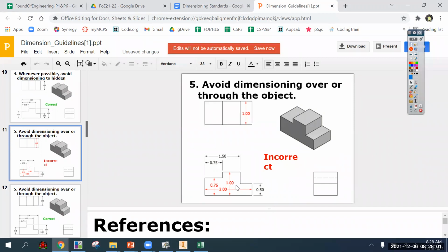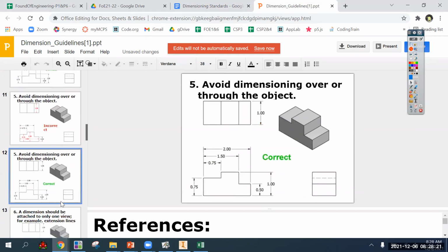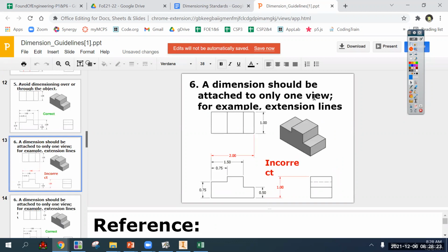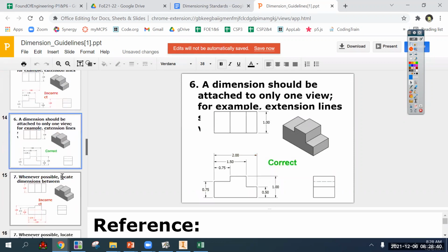Okay, so try to keep your dimension lines, and the dimension lines technically are just this part right here. Or those are, excuse me, extension lines, dimension arrows. Don't worry about the details. But we're trying to keep our views clear as much as possible. You never, like this is barely even a rule because there's no reason to ever do it, have extension lines touch or connect to other views. No reason for that. Let's fly through the rest of these.